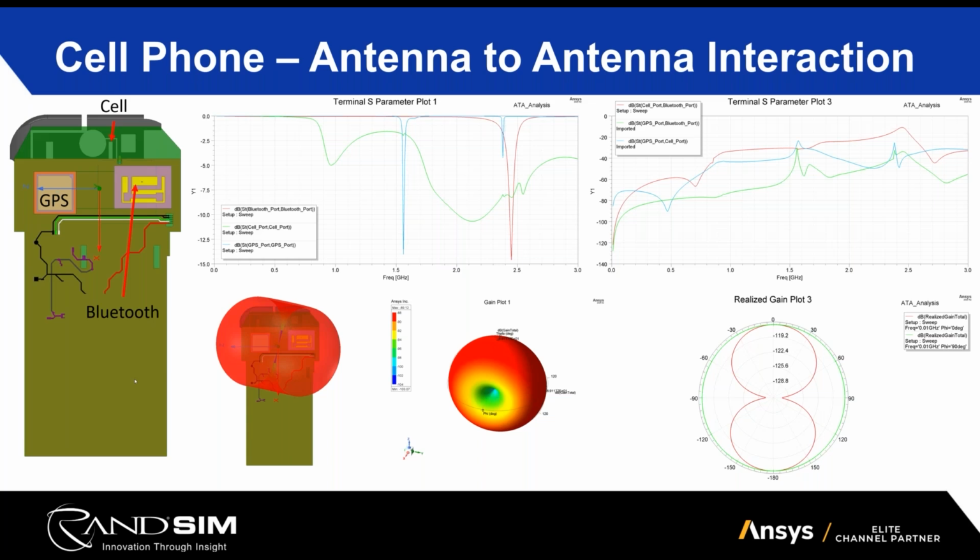Because one common gotcha, if you will, especially for people who are new to designing these types of things, if they're using an off-the-shelf antenna, your ground plane, the dimensions of your board, may be different than what they measured it on for their test board. And that can make a big difference on the radiation pattern and the gain. So helping understand that, and then also seeing how the actual coupling between them is indicated.